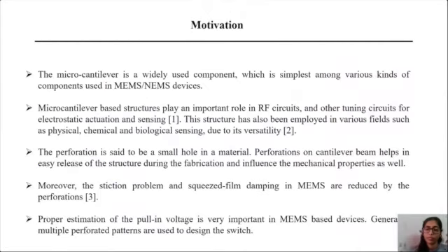We all know that microcantilever type structures, which are fixed from one end and free at the other, are the most widely used components for MEMS and NEMS devices. And along with microcantilevers, perforations, which are small holes in the material, are also used in MEMS for various requirements like low squeeze film damping, low stiction problem, easy release of the structure during fabrication, and so on. Therefore, the design and analysis of perforated microcantilevers becomes important and interesting at the same time,